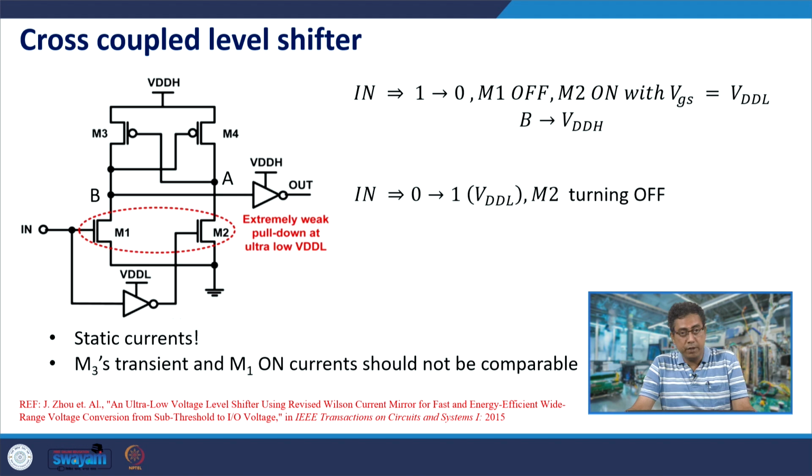So, why are these level shifters important in the near threshold voltage regime? This is because different modules, different parts of an IC, could be working in different VDD domains. So, you would need to change the logic voltage levels when moving from one VDD domain to the other, especially logic level 1. Its value would change when moving from one VDD domain to another.